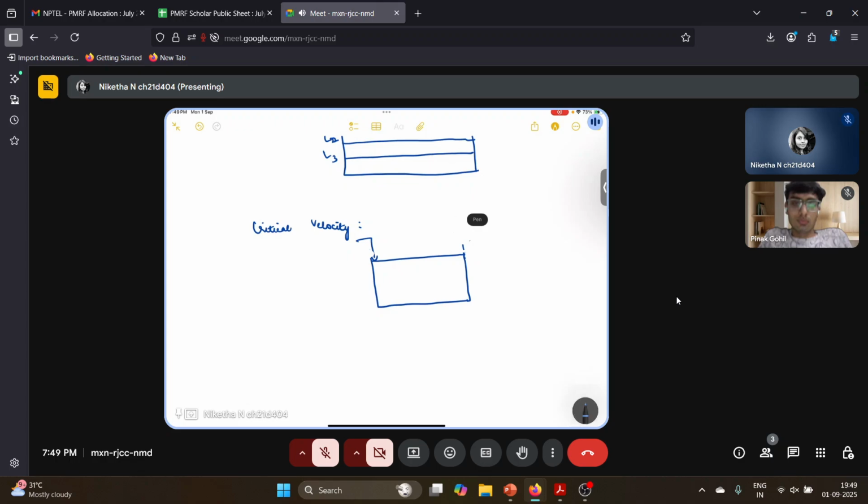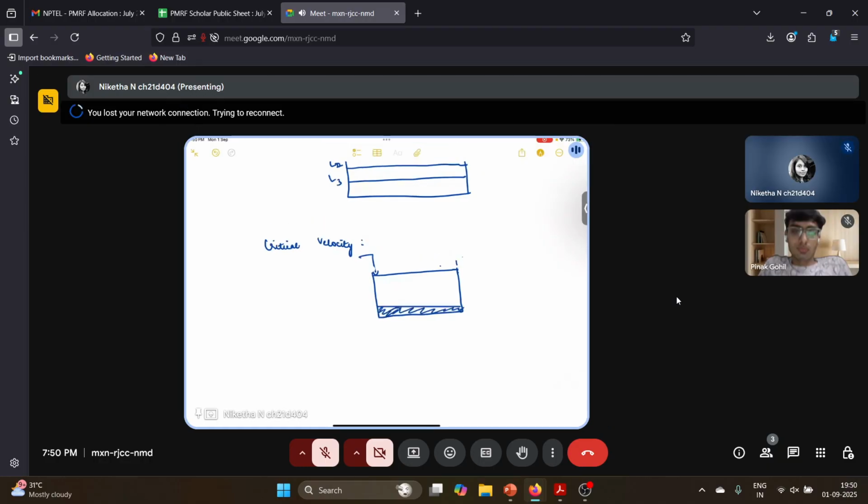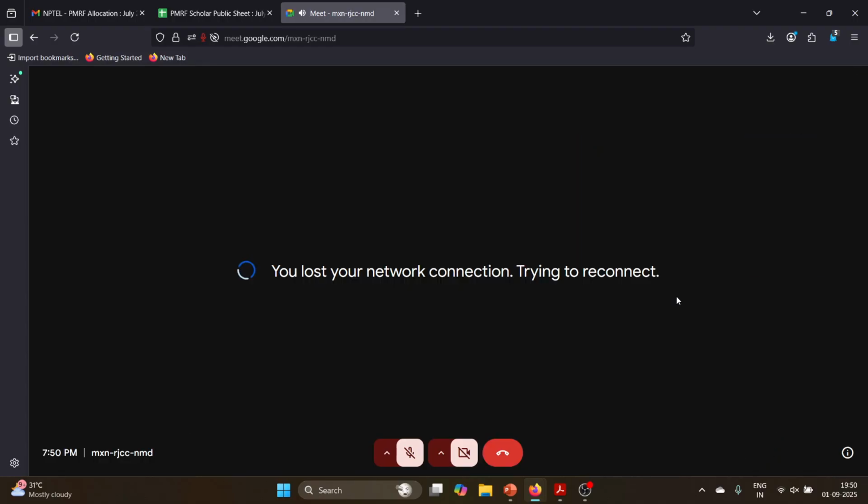After some time, when there is sedimentation of particles here, if your flow velocity is so high that along with water, whatever solids had settled, even those solids will come and mix back into the solution. Imagine the water force is so high that it will carry the settled solids also, and it will move up.